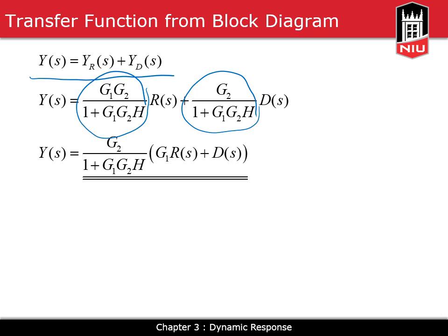So remember, whenever you have two inputs, find the transfer function from one of the inputs to the output, assuming the other one is 0. Then do the same thing for the other input. At the end, you need to add up the parts of the output that are created by each of the inputs, like what we did here.